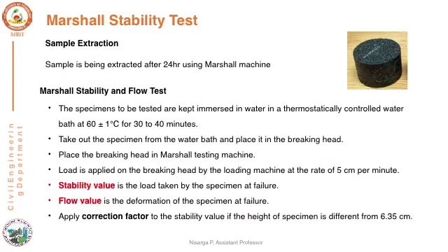The compacted specimen is then extracted after 24 hours, to ensure that the complete cooling of the bituminous mixed material is done. That sample we have prepared, the compacted specimen, has to be extracted. You can use the manual extractor or the Marshall machine. Extractors will be provided. Using either of them, you can extract the sample.